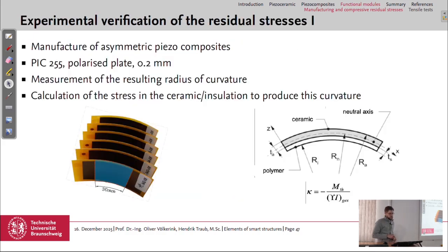These residual stresses can also be tested experimentally. A simple test is to manufacture asymmetric piezocomposites. So we have on one side the ceramic and on the other side the polymer, and with different residual stresses in the different layers, we get curvature after cooling it down.